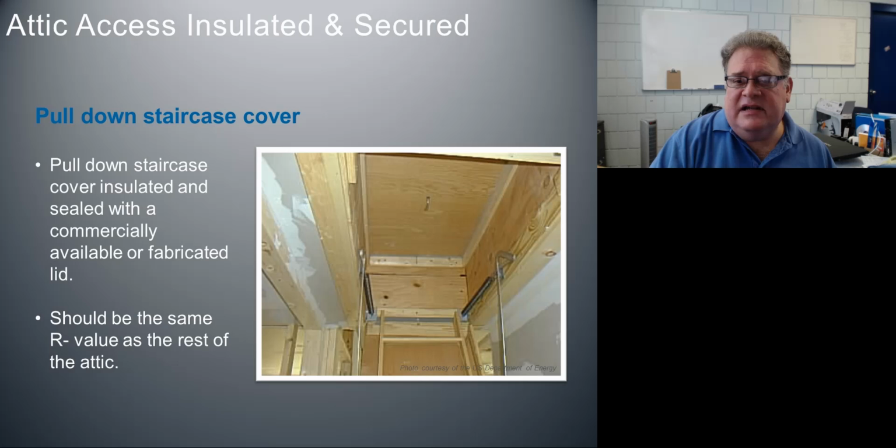Alrighty, pull-down staircase cover. Here we've got a good one. It appears to be weather stripped back here. It's sealed with a commercially available fabricated lid or with something that is site built. Sometimes you can just build up levels of 1 inch foam.